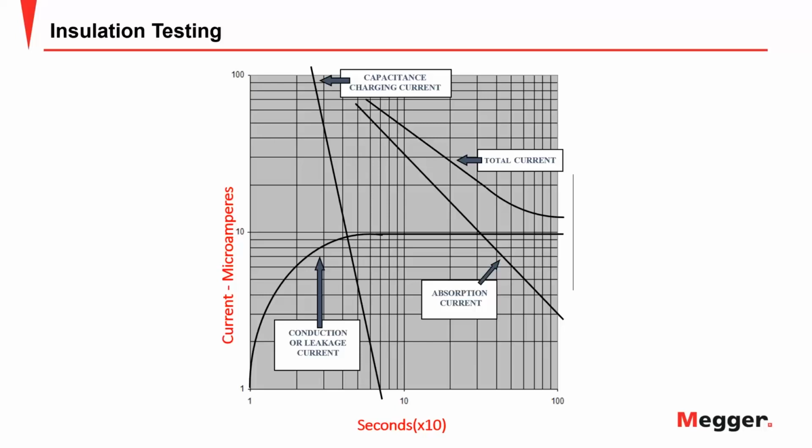It occurs quickly because it's in metal, which is a good conductor. That's why on your old analog testers, the pointer would always peg low at the start of the test. It's seeing the capacitive charge, and very quickly that would charge up, and then the pointer would start rising back up to the high end. So capacitance starts high, goes to zero, and does it relatively quickly.